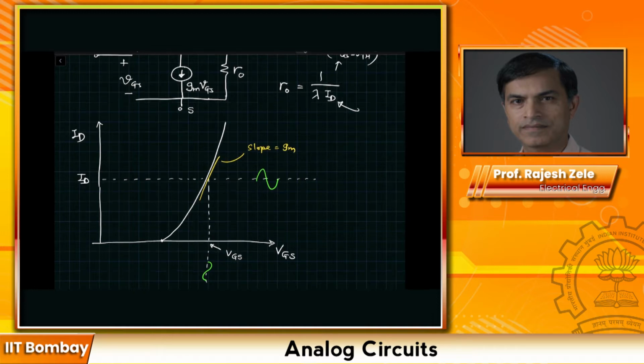However, there is inversion when you look at the drain voltage, because we again have the output voltage at the drain given by VDD minus ID times R. That generally happens when you have a resistor and this is your VDD. When you look at the output voltage, there is inversion. However, if you just look at the drain current, then there is no inversion.